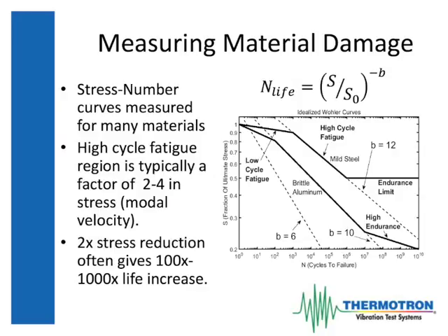As you come down in stress a little bit more, you enter this high cycle fatigue region, where the product isn't macroscopically deforming as the test progresses, but rather microscopic cracks are propagating through the material until they reach some critical length, at which point the next stress cycle causes an uncontrolled energy release and the product fails.